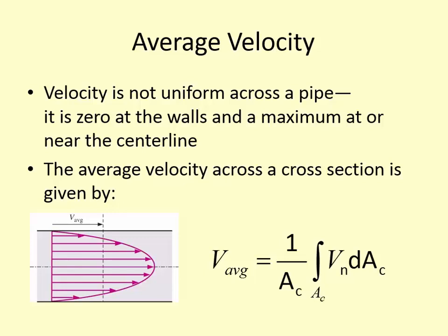So we're finding this average velocity. Again, we don't often have to do this because in many cases we don't necessarily know the profile of how the velocity is changing across the cross-section. And if we can measure the fluid flow or somehow that average velocity is just given to us, then it's easier in practice to just use some lump average velocity rather than integrating every time.